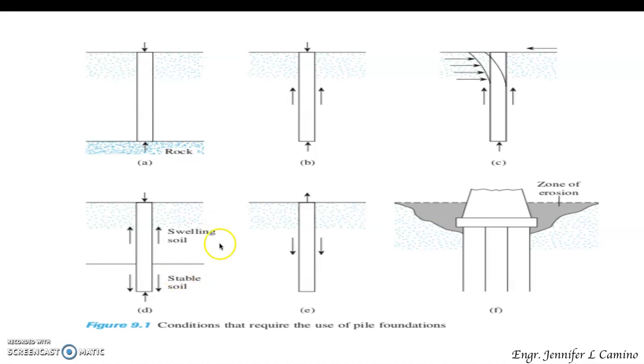Expansive soil swells and shrinks as its moisture content increases or decreases, and the pressure of the swelling can be considerable. If shallow foundations are used in such circumstances, the structure may suffer considerable damage. However, pile foundations may be considered as an alternative, with piles extended beyond the active zone,